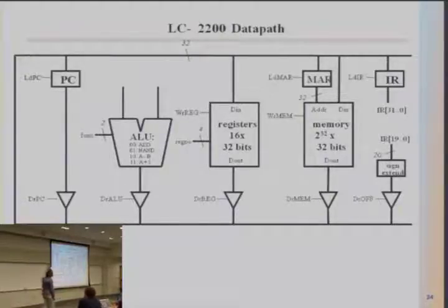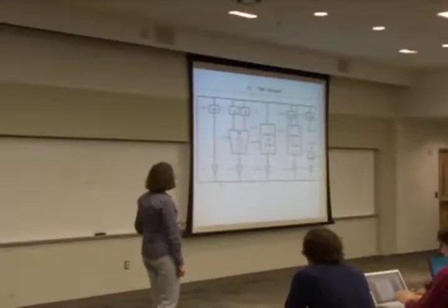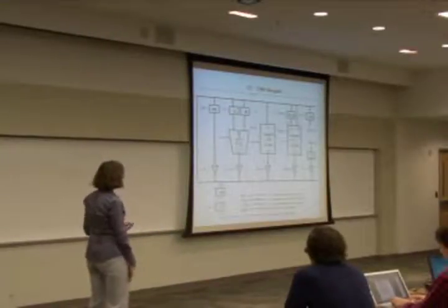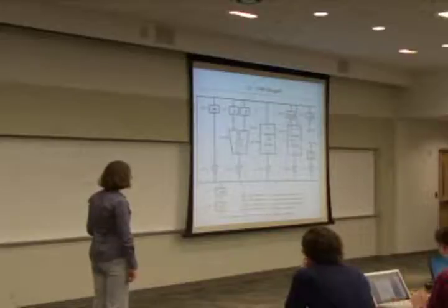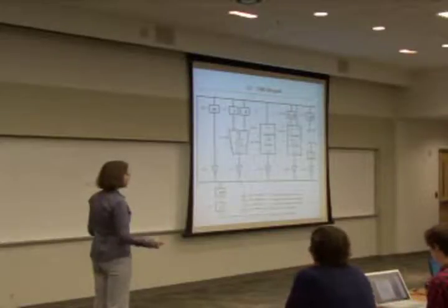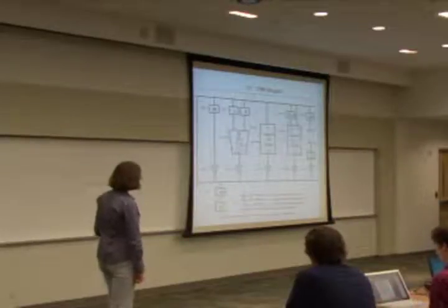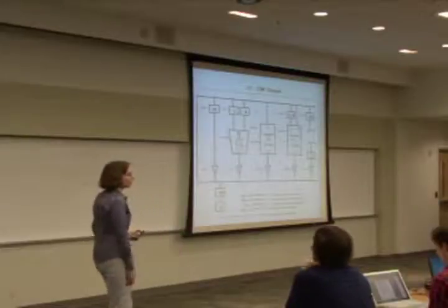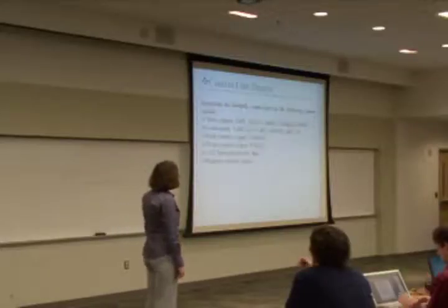Then the next step is to store in register A our information, and then to load in register B, which is RY and RZ, and then we add the numbers, and that completes pretty much our data path. The last thing that we missed, and we'll see later why we need this, is a 1-bit register Z. If you have any question like, is A equal to B, if it's true, then Z will be 1. If it's false, it will be 0, and that will help us jump or branch and so on. So that's the data path.